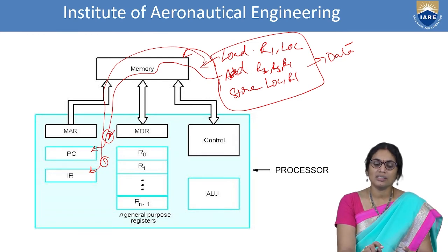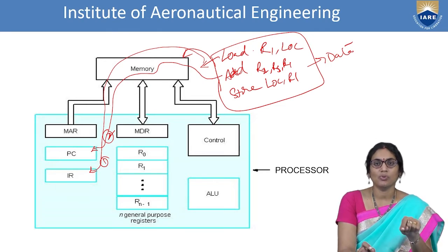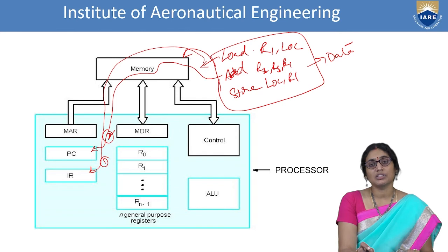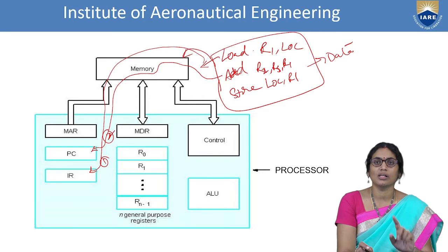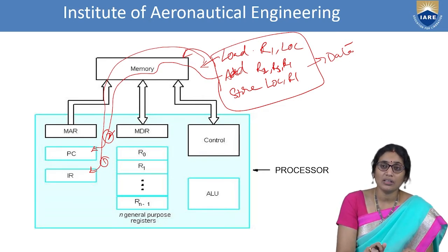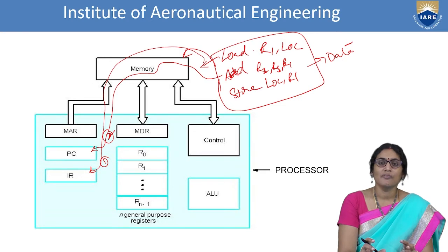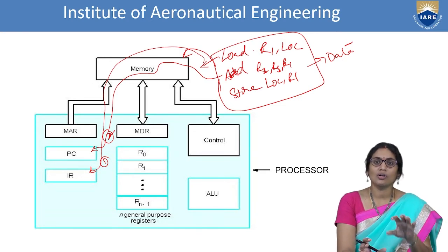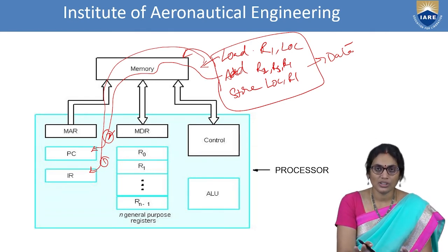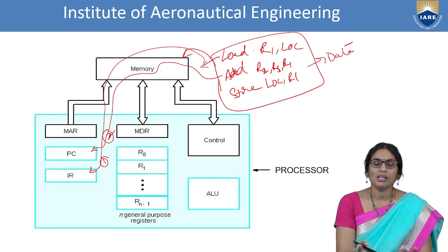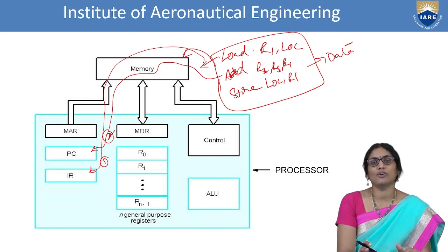So the memory is being fetched for the second instruction in the program and it is held in the program counter. That means the current instruction which you are running is loaded in the instruction register, and the next instruction which you have to execute should be loaded in the program counter. Why are you making this ready with the external components? Because we are getting things ready in order to increase the speed of the processor as well as decrease the time to execute the program. So in order to synchronize with the operations inside the program execution, we make this faster in order to increase the speed of the processor.